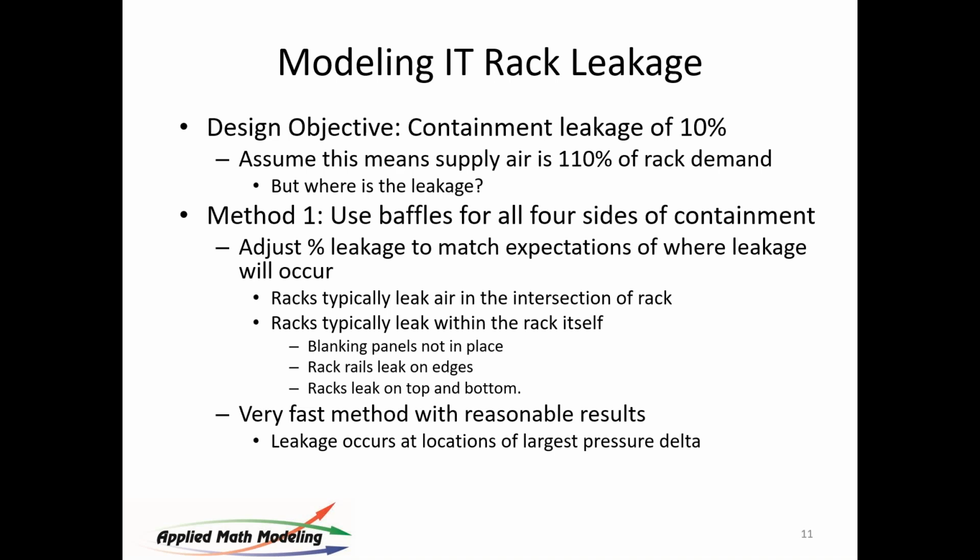So for those of you who are designing or providing feedback to people who might be wanting to rent space in your co-location facility, drill on this a little bit. Try to find out what they mean by percentage because it's an important component. What you can do with baffles is adjust the leakage to match the expectation of where it will occur. So if they're expecting 10% of CFM, for example, you can just adjust the baffles until 10% of the air supplied by the air handler is leaking through the baffles. We'll show you how to do that.